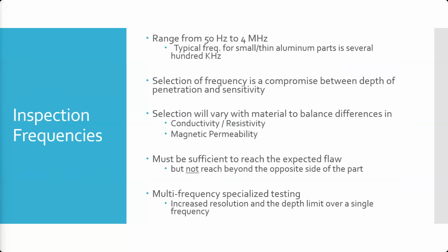Actually, we'll look at probes in more detail, but here is a high frequency surface crack probe. Here is a low frequency side corrosion probe. What do you notice about them? The low frequency is bigger. The coil size directly correlates to the frequency you're going to run at.